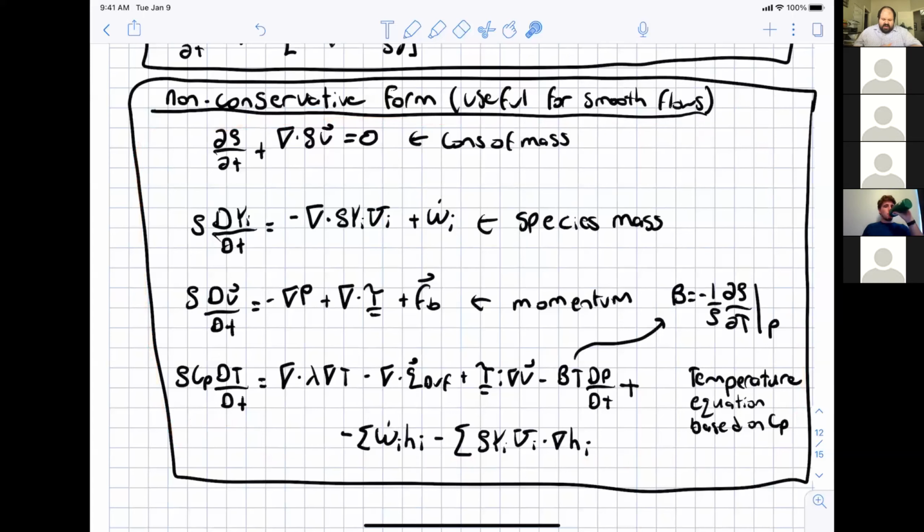Now note, every now and again when I review a paper, and you'll find this when you work through problem 5, the specific heat naturally goes outside of the derivative. It does not go inside of this derivative right here. Even though c_p is outside of the time derivative, this expression is valid for cases where the specific heat is non-constant.